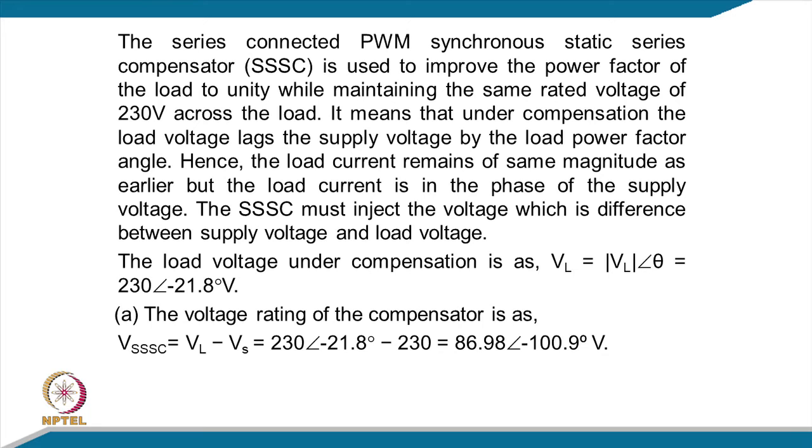So, the SSC must inject a voltage which is the difference between the supply voltage and the load voltage. The load voltage under compensation is V equal to 230 at an angle of 21.8, and the voltage rating of the compensator will be VL minus VS. So, this is the VS and this is the VL. You will get this injected voltage as 86.98 at an angle of 100.9 degree.